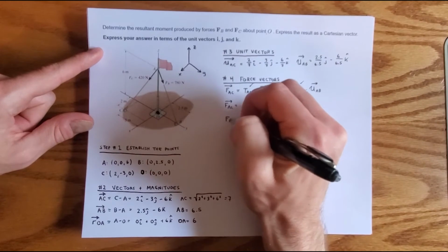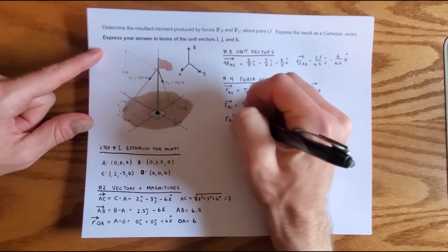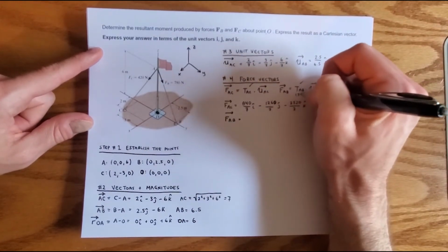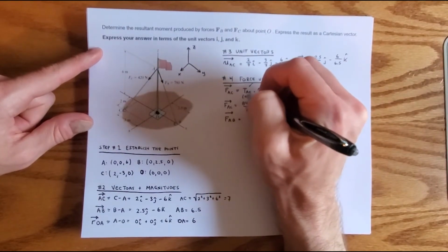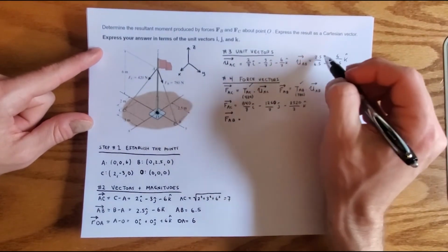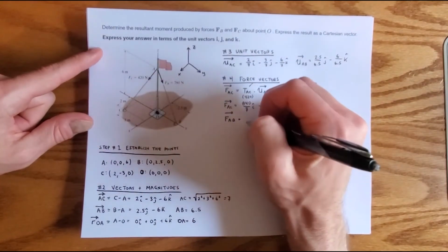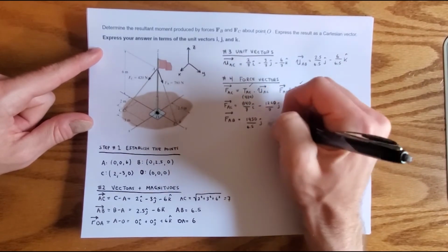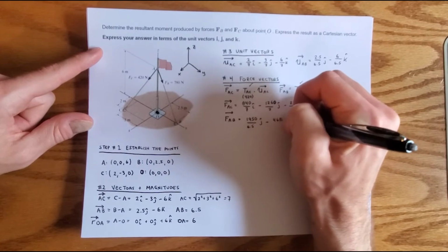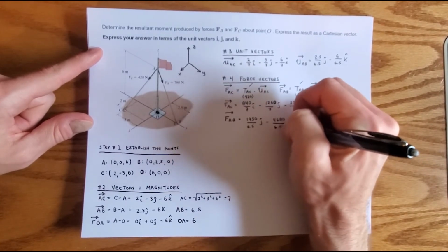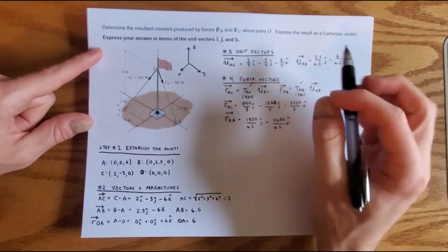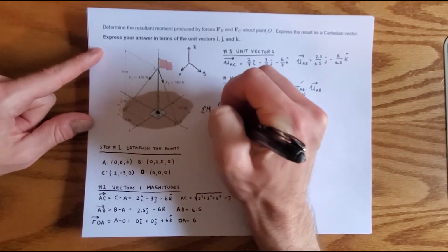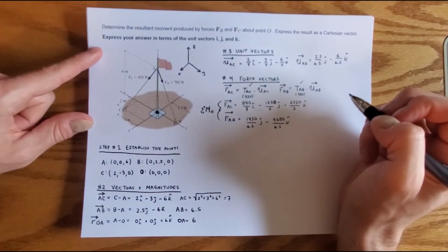And if we look, we have force AB, which is going to be equal to 780. So let's just write that up here so we don't forget. And you know where these numbers are coming from. But it's going to be 780 times 2.5 over 6.5. So the value we get over here is 1950 over 6.5j minus 4680 over 6.5k. Now these are our two forces that are going to be causing moments about point O, which is the question we're trying to solve for.